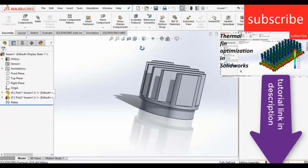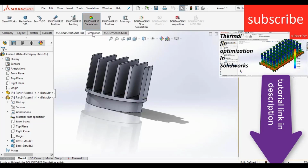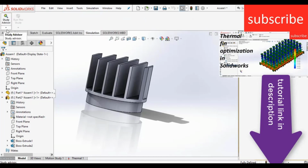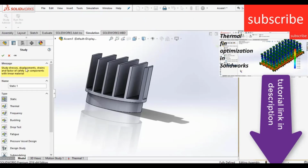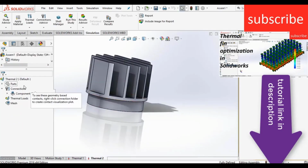So exit the assembly edit mode. Now in the geometry, what we can do is go to the simulation tab. If you don't see it, click on SolidWorks add-ins, click on SolidWorks Simulation. Now click on simulation tab. Now click here, click on new study. Remember, I am also going to show some mistakes that beginners make, so make sure you watch the video carefully.